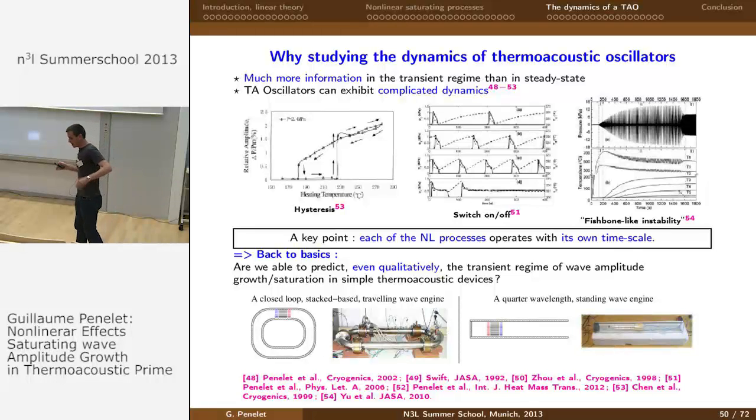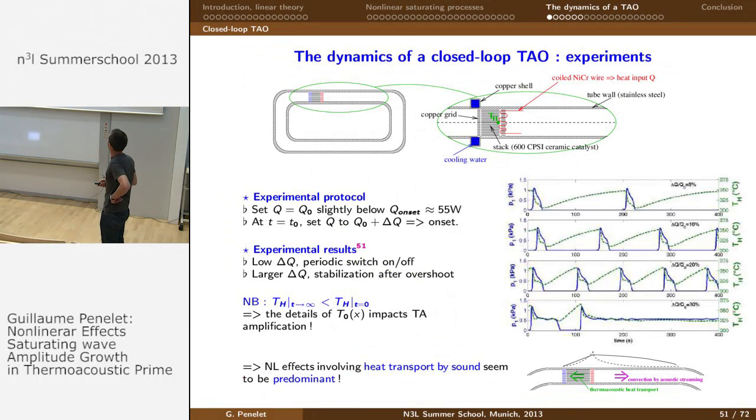A key point is that each of the processes that I have discussed operates with its own time scale. And so due to this, we can get information on these processes in the transient regime. So let's go back to basics and ask if we are able to reproduce the dynamics of the wave amplitude growth in a simple device like the closed loop stack-based traveling wave engine or even the thermoacoustic laser. So let's begin with the closed loop thermoacoustic engine.